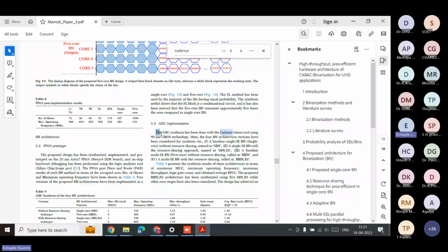No need to mention whether it's GPDK, TSMC, UMC, SCL and all. If you mention that, then it's going to be a particular technology like TSMC, a kind of publicity. Instead of that, you can just give the technology node. If you search some documentation, you will find GPDK 45 nanometer is absolutely equal to the TSMC 45 nanometer. The only difference is that GPDK is meant only for research and learning and teaching purposes.